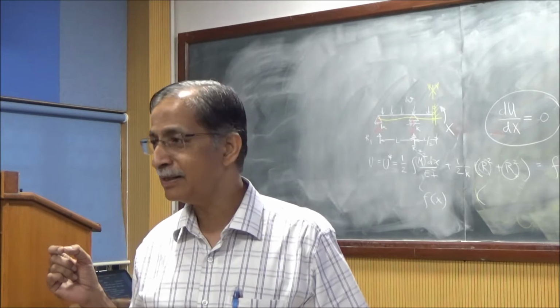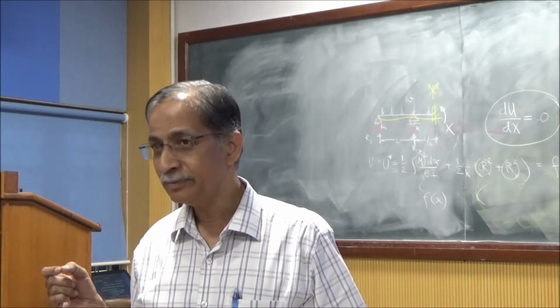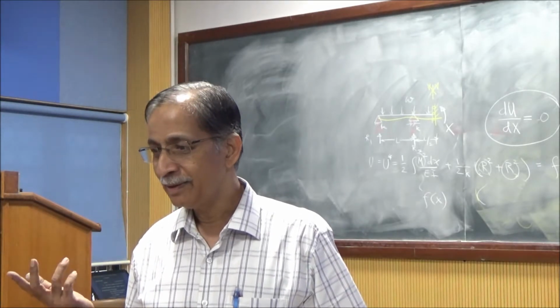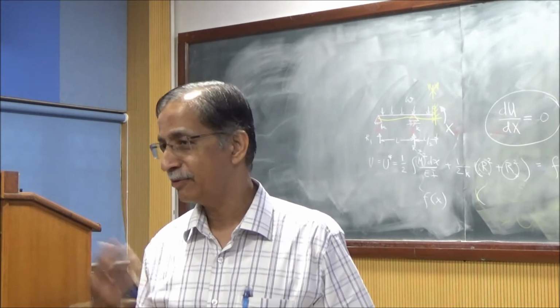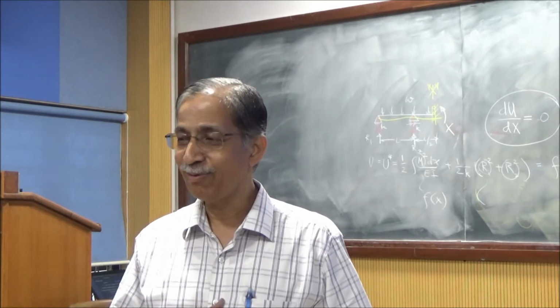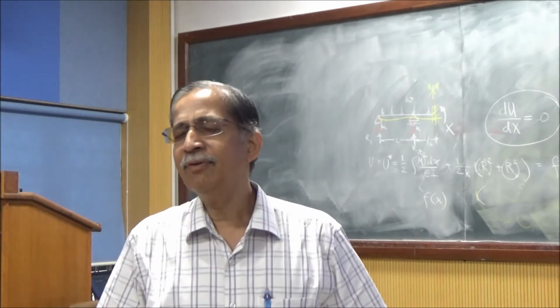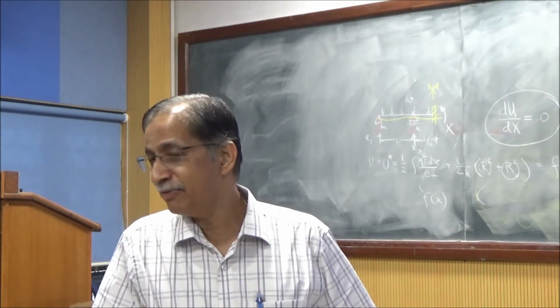E, modulus of elasticity. If modulus of elasticity is low, it's a direct reflection on the grade of concrete. And those tests were done in IIT Delhi. They took cores and they found that the grade of concrete from M30 on the ground floor became M10 on the top floor. For various reasons, we won't get into that. Now that's a challenge. You've got a punching shear failure.